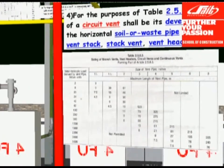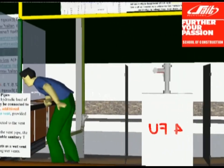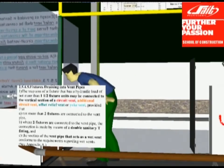You can dump up to 2, 1½ inch diameter trap arms with a hydraulic load of 1½ fixture units each into the wet part of the circuit vent. In this case the wet portion of the circuit vent would have to be at least 2 inches in size, due to the 3-inch traps on the toilets.